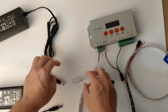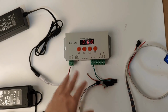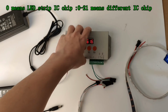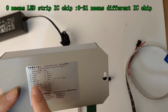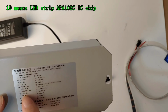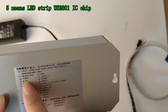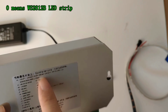Let's power the controller. You will see there are many numbers. The first number means the LED chip type, and you can read the description on its back. 19 means APA102, 5 means WS2801, and 00 means WS2812B.